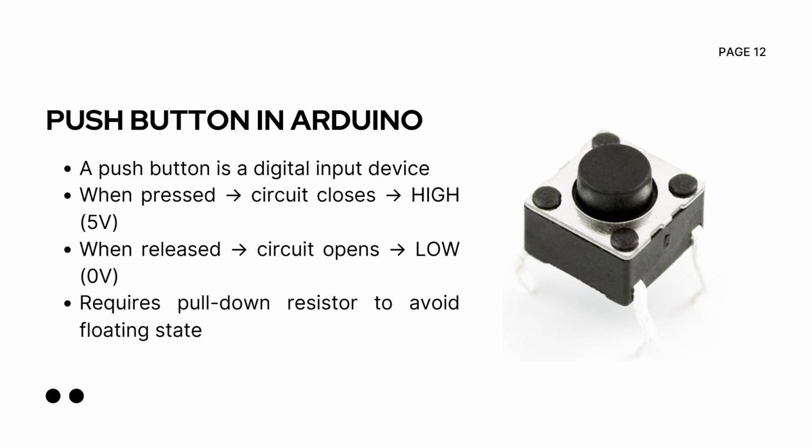Push button in Arduino. A push button is a simple input device. When pressed, the circuit closes and the pin reads high. When released, it reads low. To avoid random signals when the button is not pressed, we use a pull down resistor.